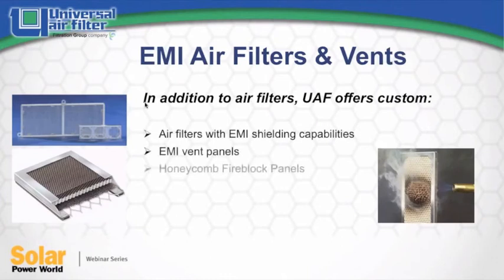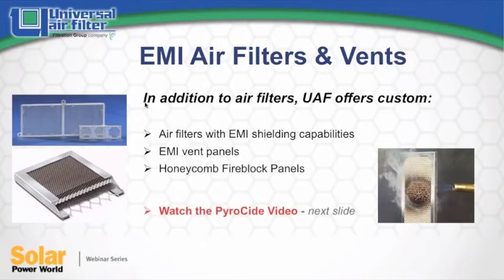By its very nature, utility scale equipment commonly consists of high voltages and generates electromagnetic interference. You should know that openings and cabinets needed for fresh air intake can be configured with air filters that include EMI shielding. Integrated assemblies promote SKU and vendor consolidation and also save on space. EMI panels for exhaust openings with no need for dust filtration are also popular in cooling systems that run 24/7.